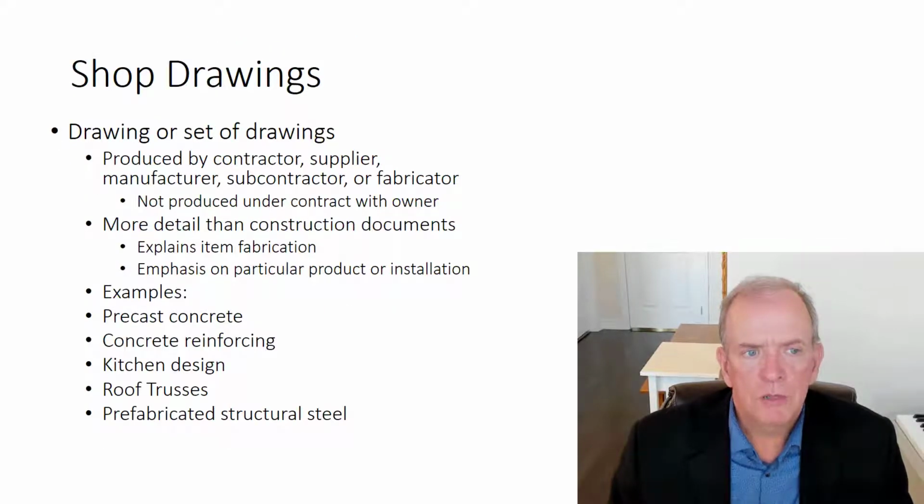So shop drawings, really, a shop drawing is the manufacturer's intent of how their product is to be installed. For example, if we talk about a house, the manufacturer of the roof trusses will do shop drawings for the roof trusses, and it'll show the strength characteristics of the trusses. It'll show basically where the webs are supposed to be located, the size of the chords. It'll indicate the calculations for the snow loads that it's capable of carrying, and it'll show and indicate how it